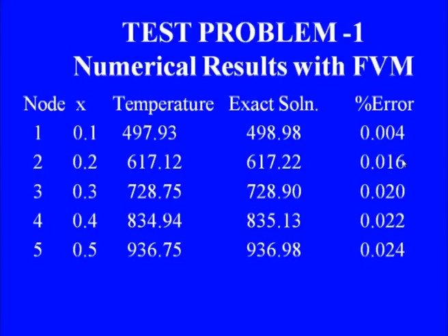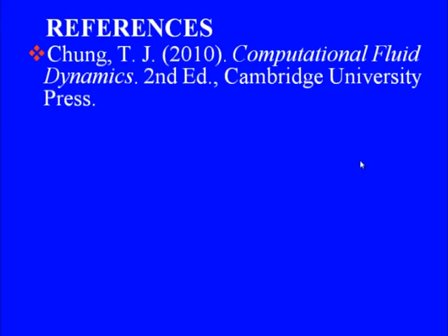And the reason was very simple. In finite volume formulation we have used second order accurate schemes everywhere, whereas in the case of finite differences at the boundaries, for the flux term we had used a backward difference approximation which was only first order accurate. So, we will stop here with our discussions on finite volume method,